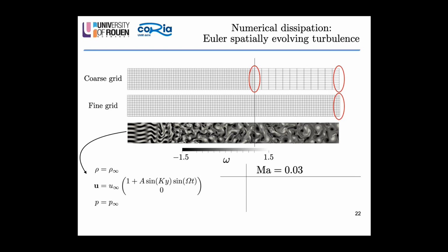So we consider also two different Mach numbers, a small Mach number and a relatively high Mach number, and two different Riemann solvers, which are essentially numerical fluxes in discontinuous spectral methods: the Roe solver and the Lax-Friedrichs flux. We took these choices because for relatively high Mach number, these Riemann solvers both behave as upwind fluxes, but in the limit of small Mach number, the Roe solver is still upwind, and the Lax-Friedrichs flux behaves as a hyper upwind flux.